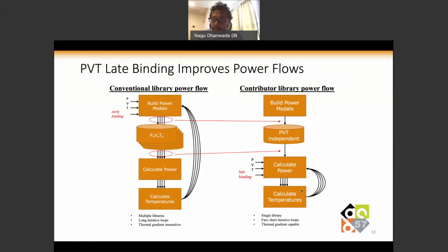So the PVT conditions are applied during power model generation itself, right? Which leads to us requiring a large number of circuit simulations, and the fact that the power analysis is specific to a particular PVT. If you need analysis done at a different PVT point, then you would have to do some interpolation and extrapolation to actually accomplish that, right?